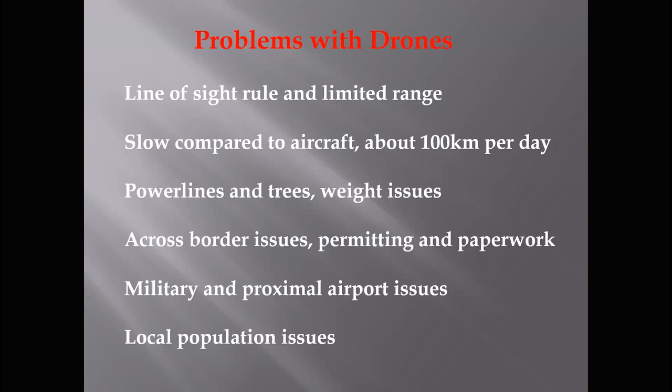Say you're in Botswana, you can only really see that drone for, if you're lucky, a couple of 100 meters at a time. So then you have to build a platform in the area, or it's just not realistic to fly 500 meters at a time. You want to try and fly blocks with a drone of 2 kilometers by 1 kilometer wide and then merge all the blocks together, something like that.